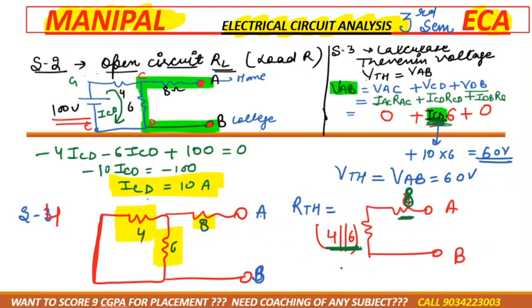Now they are on the same path. So what can we say for RTH? That is 4 parallel 6, 4 into 6 divided by 4 plus 6, plus 8. So it would be 24 divided by 10 is 2.4 plus 8, that would be 10.4 ohm. So now we got the value for RTH also, that is 10.4.